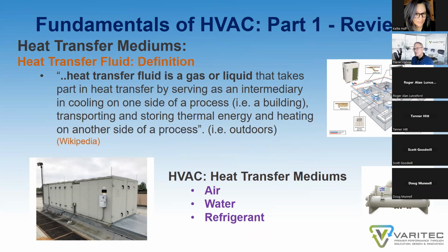So a heat transfer fluid is a gas or liquid that takes part in heat transfer by serving as an intermediary in cooling on one side of a process, transporting and storing thermal energy, and heating on another side of the process. We examined how there were 3 heat transfer mediums available: air, water, and refrigerant, and we demonstrated that the primary heat transfer medium for a building in a conventional HVAC system is air.